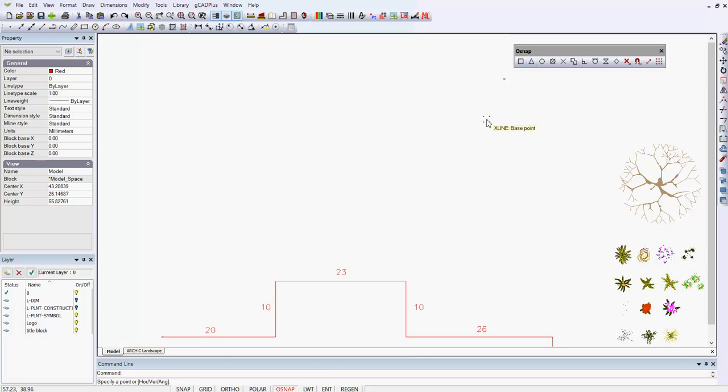When I click it once, it'll one time only find the midpoint there, and now I'm swinging to show the software where I want this construction line to be. You can see I can't lock it into the vertical until I pop down and put polar on, and now I can lock that construction line into vertical, and I'll right click and exit.